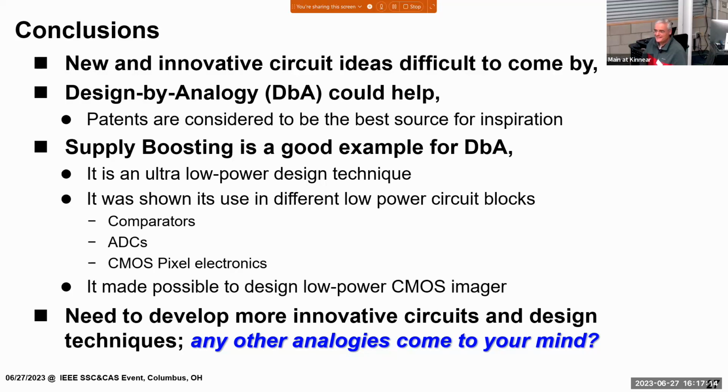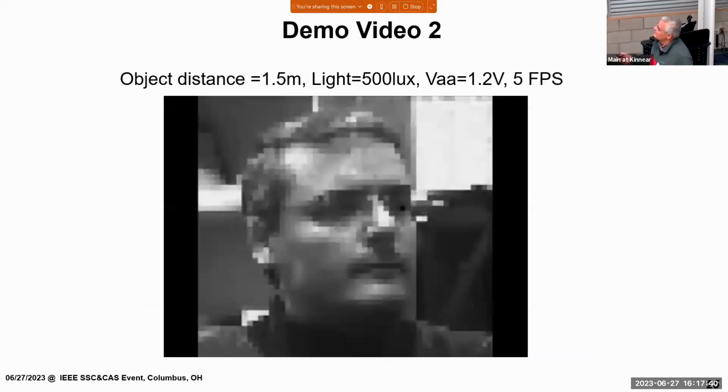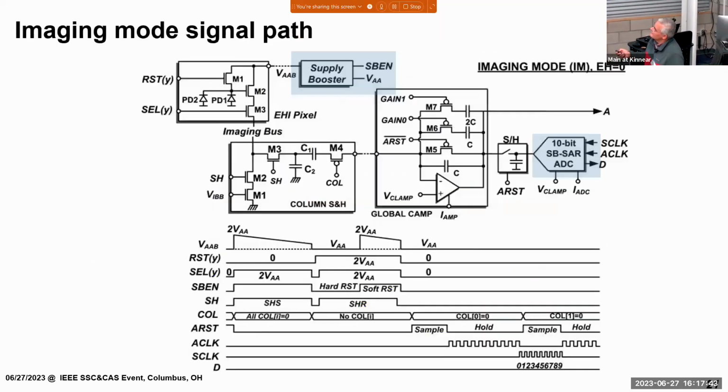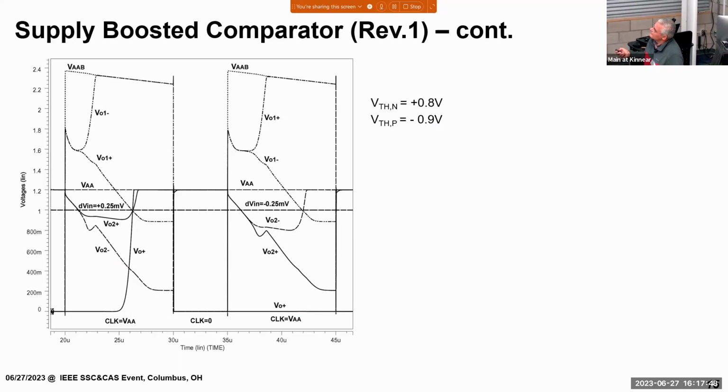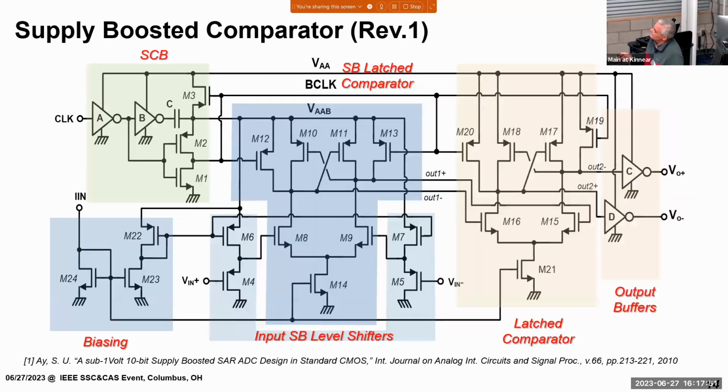Okay, so I love analogies too. But I was thinking about the shower idea: you go in when you have voltage or pressure, and if that pressure changes, you're still okay. That didn't quite help me see the comparator circuit and why it has such good power supply rejection ratio. So if you can go back to the comparator circuit, because I think what you're saying is that even if the boosted supply voltage changes while the comparator is making a decision, it still makes the same decision, right?